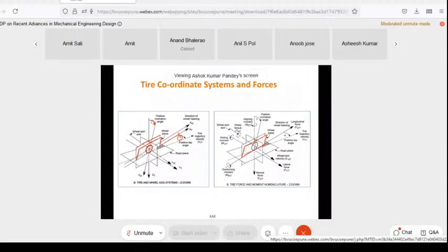So in this particular plane, this is your inclination angle, and this terminal force is in the direction of the wheel, in the instantaneous direction of the wheel, I would say. So here your longitudinal force will be generated along the wheel plane. Then you have lateral forces which are generated over here. This is called lateral force, and normal force which will be generated over here.